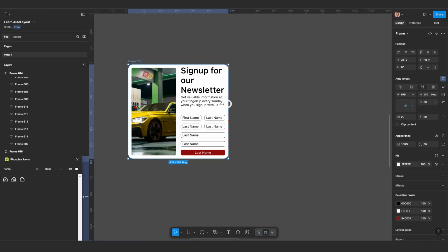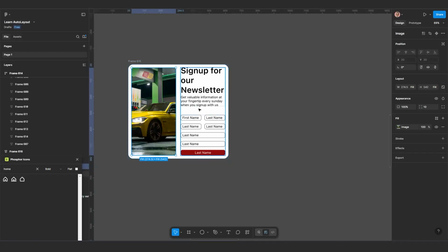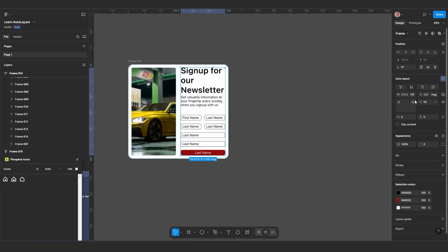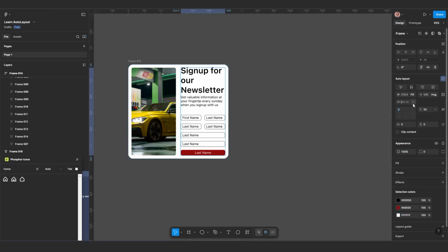So here I'm going to set this guy, you can see this size here. I will come here and say add minimum width. That means once you get to this extent, don't resize again. So I'll select and add minimum width. I can type the number here, but I can click and say set to current width. That means the current size will now appear here, and I will select this one too, click here, add minimum width, and select current width.